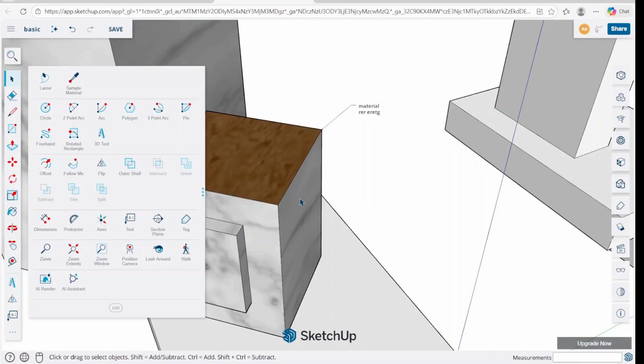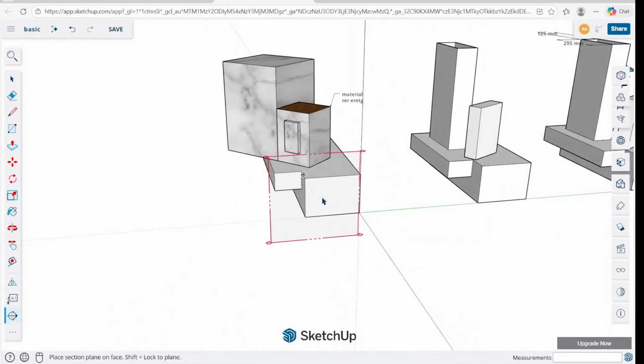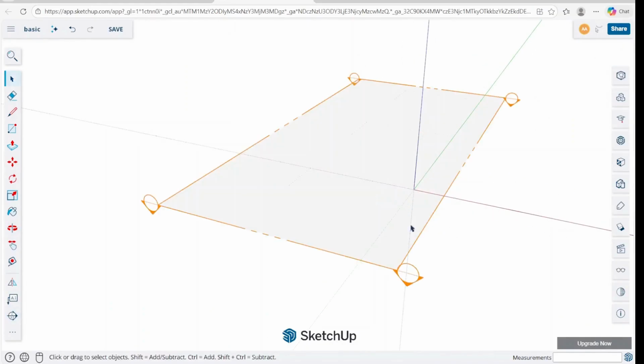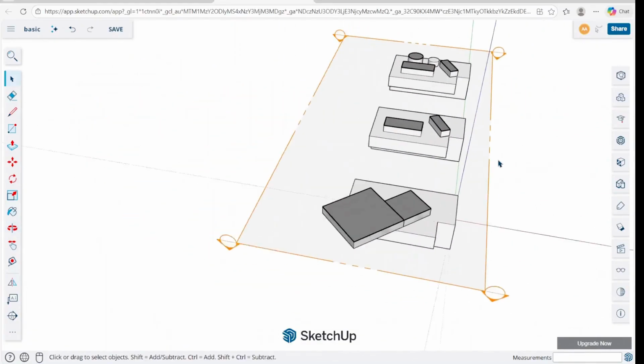If you need to do a sectional view of the plan or elevation, you can do so with the section command. You need to create scenes to hide and unhide the section symbol using layer, or activate and deactivate the section for each scenes.